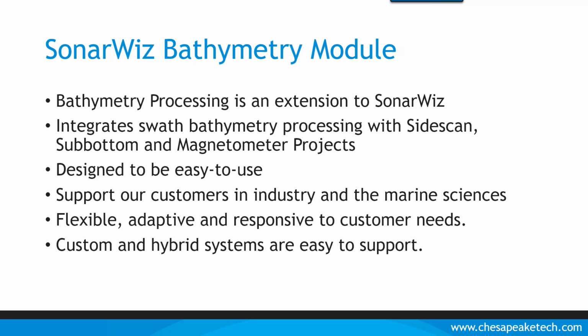So as part of that, we've needed to build the SonarWiz bathymetry to be flexible, adaptive, responsive to your needs. We are dealing with a lot of custom and hybrid systems, so we've tried to come up with a processing workflow that is easy to modify and easy to add support for new systems, and is flexible enough that it can deal with old systems that are analog all the way through new stuff that hasn't been fully calibrated yet. We basically operate from the assumption that most of the systems we're dealing with are not calibrated, which has some impacts on what algorithms we can use and what our results will look like.